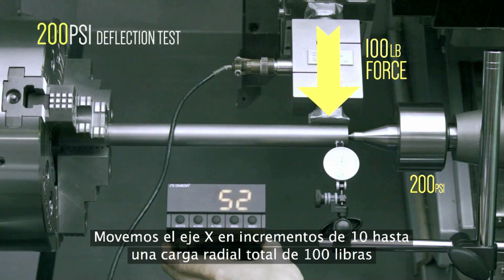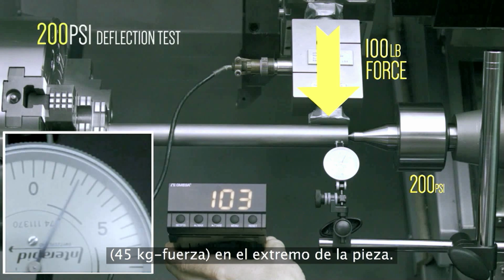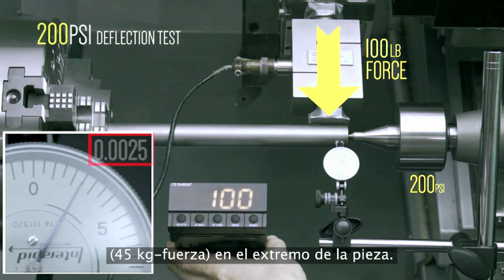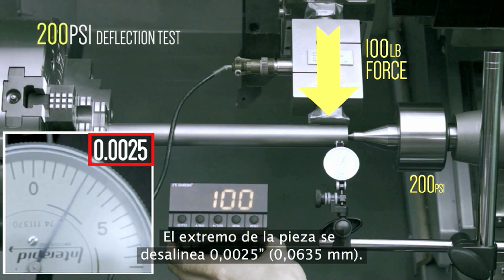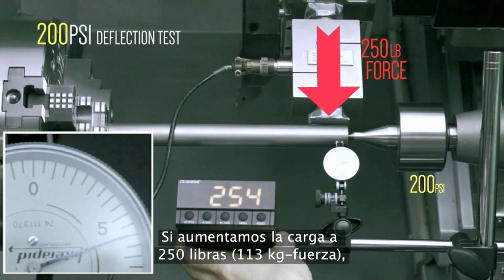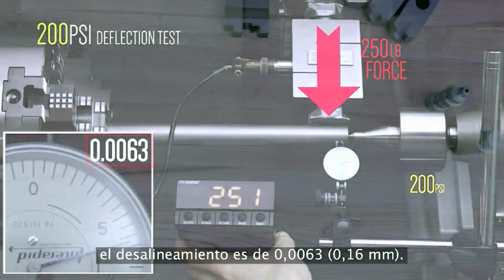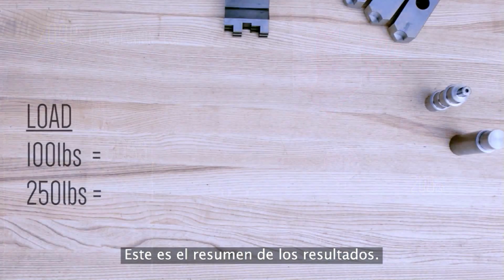Okay, so we're jogging x-axis in tenths mode to apply a radial load of 100 pounds at the end of the workpiece. The end of the shaft deflects 2 thou 5 tenths. Increasing the load to 250 pounds of force, we get a reading of 6 thou 3 tenths. Here is a summary of these results.